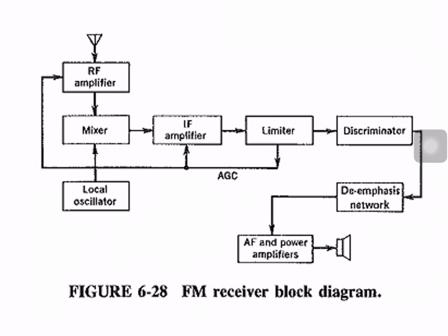Or a cascode amplifier can be used to match the input impedance of the antenna with the RF amplifier. Both types have the property of low input impedance, matching the antenna. So that's why we generally use grounded gate, grounded base, or cascode amplifiers.